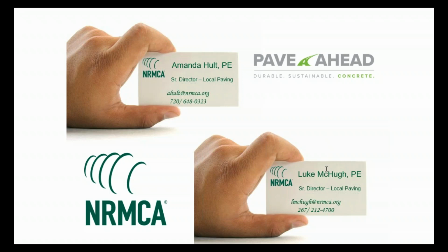One that I personally have worked on is a situation where there's a lot of sawdust that has been created and is basically just left to lay on the ground. You don't want those types of joints to be exposed to that material. Also, if your site layout is in more of a valley type formation, and you've got a joint at the base of that V, and you've got water flowing over that joint, those are areas where you would most definitely want to consider sealing those joints. There are some details included in the guide that will help you along with that.